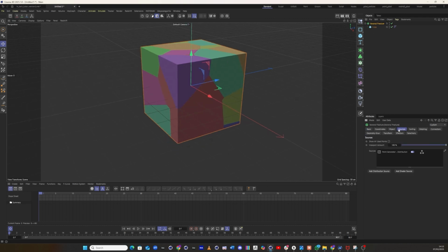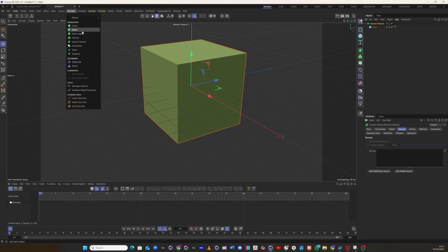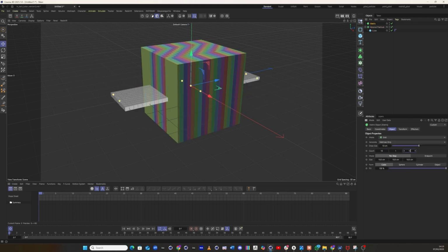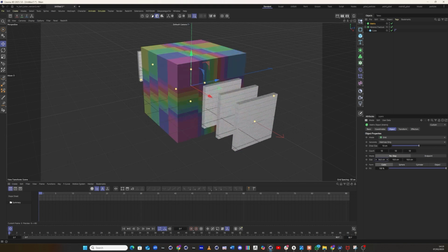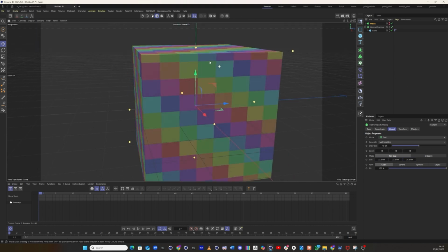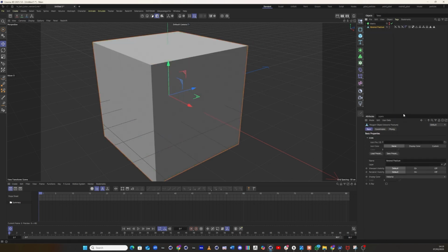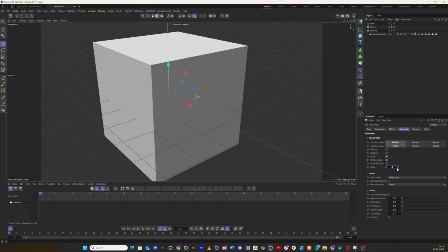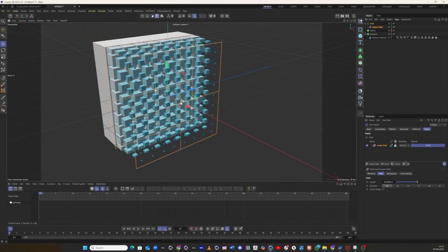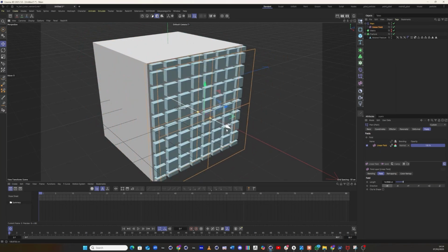First, place the cube under a Voronoi object, then change the source to a matrix grid and adjust the size to match your needs. You'll see the elements are now connected in a square pattern. After making the object editable and reconnecting it using the standard fracture tool, you gain precise control over these newly created divisions. This setup gives us an additional advantage.